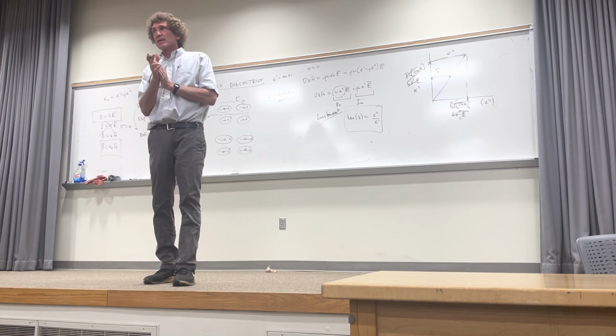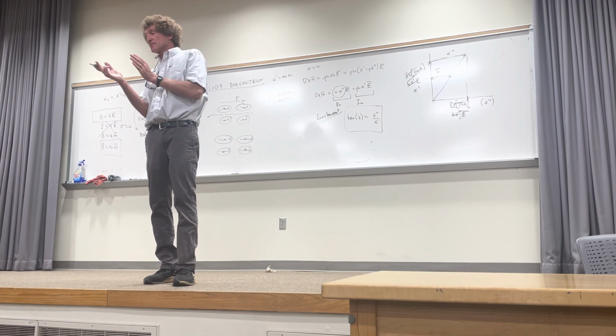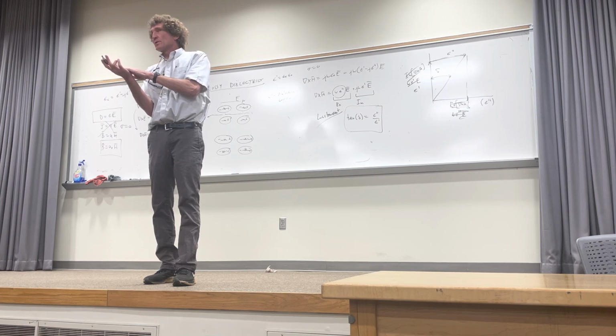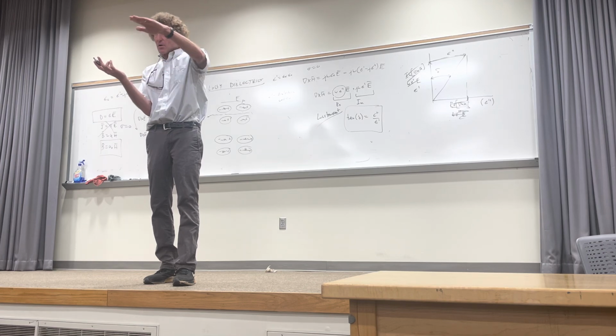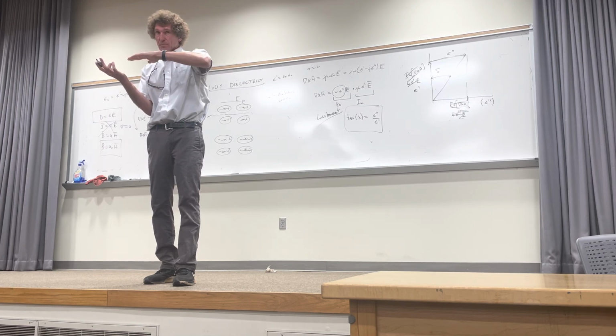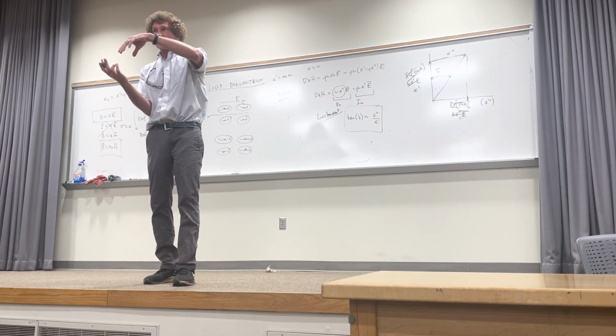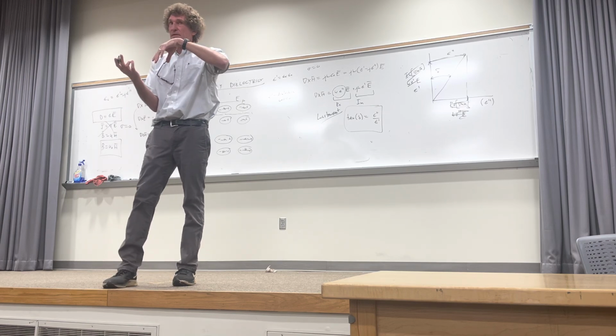Please remember this. If you're ever involved in looking at materials, you want low loss materials. The best example of this is any type of coplanar circuit board, or FR4 board, or anything like that. We have a copper clad and a dielectric and copper backed, right? And you mount components and then etch off the copper you don't want, and you have circuitry. Do y'all follow me on this? It's like lithography for VLSI technology.